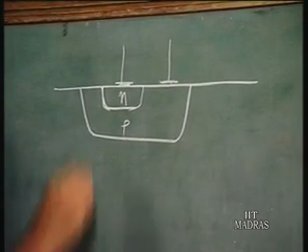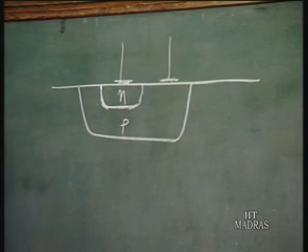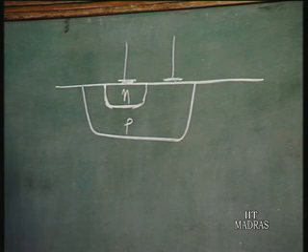And the delay in a circuit, as we have seen, is dependent to a large extent on the emitter base junction capacitance, which means of course the junction capacitance as well as the diffusion capacitance.